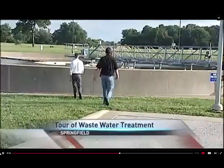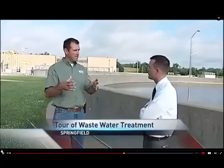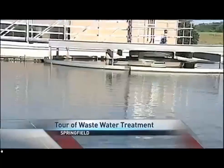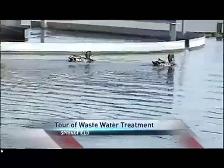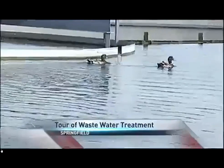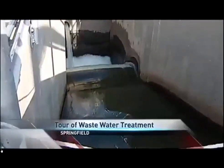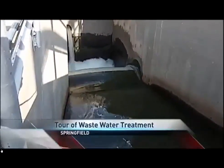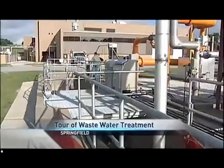Now we're in the clarification step. So what we do is we bring that water out of the aeration basin with all those microorganisms in it, bring it in here, and we slow the flow down. Those bacteria and microorganisms settle to the bottom, and the clean water filters off the top. From the clarifiers, which we were just at, the next step, it goes through a small filtration step for any fine solids. Then it comes over to our ozone disinfection.